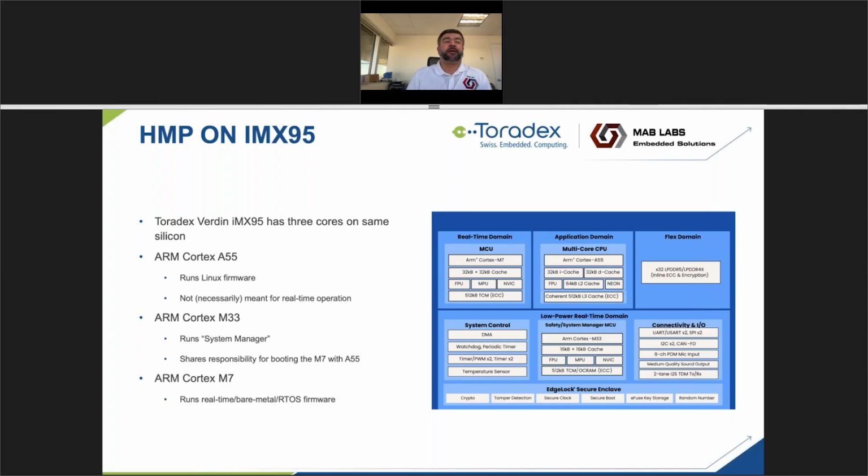And the cool thing about this is that the System Manager code base is open source. So if you need to make customizations and modifications, let's say to boot particular firmware or to control the boot processes of the M7, you can do that because the source code is available to you. And then finally, the interesting part of this particular webinar is the Cortex M7, which runs the real-time, bare metal or RTOS firmware that can be controlled by both the M33 and the A55.